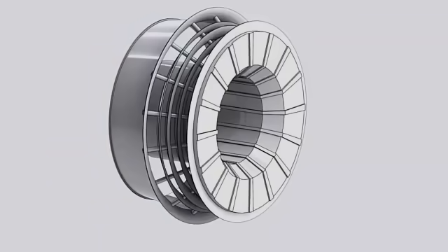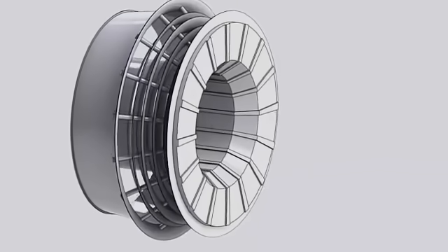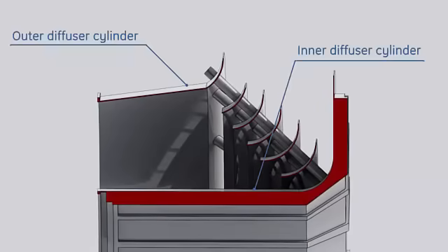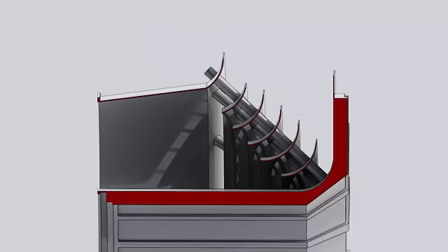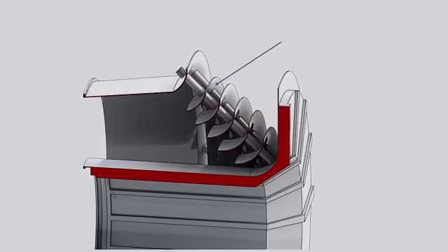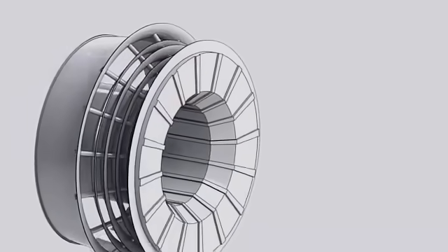The exhaust diffuser is located at the extreme aft end of the gas turbine, bolted to the exhaust frame. The exhaust diffuser is a fabricated assembly consisting of inner cylinder and outer divergent cylinder. This divergent configuration reduces the exhaust gas's velocity and increases its pressure. At the aft end of the diffuser, 5 turning vanes direct gases from the axial to the radial direction into the exhaust plenum. The inner side of the inner cylinder is isolated by insulation packs to reduce the heat transferred to the load coupling tunnel and to the bearing number 3 area.